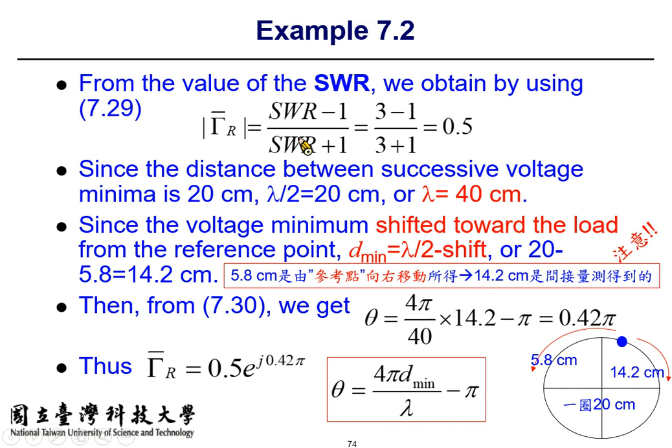So the large circle of the Smith chart is the unit circle, the circle of magnitude equal to 1. So the reflection coefficient for all possible passive terminations will be located within the unit circle.